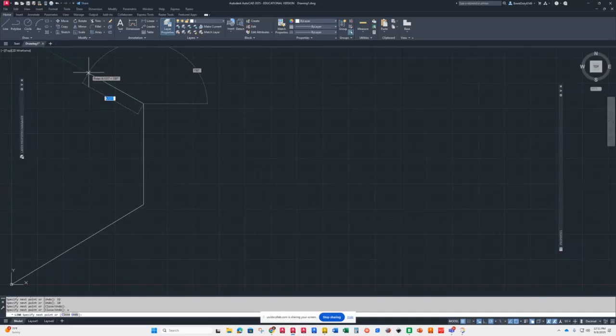Because if I'm measuring from vertical, I still have to take into consideration the 0 to 90, right? Because that's where I have to figure that out for AutoCAD. So if I was drawing it, typing in a polar coordinate, then that's what I'd have to do. I'd have to type in whatever my distance is, the angle symbol, and then the angle would be at 150. Because in space, that's where it would be. So that's what that says. That says 150 degrees. It says polar, 6 point, whatever.